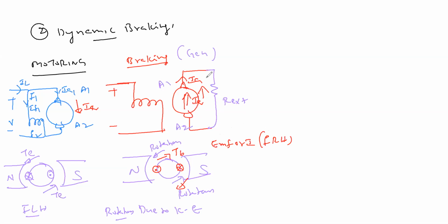So after some time, or if the R external is increased, entire kinetic energy is converted into heat energy, and the motor stops here. So once the motor stops, even if the supply is there, nothing will happen. So please mention that point.